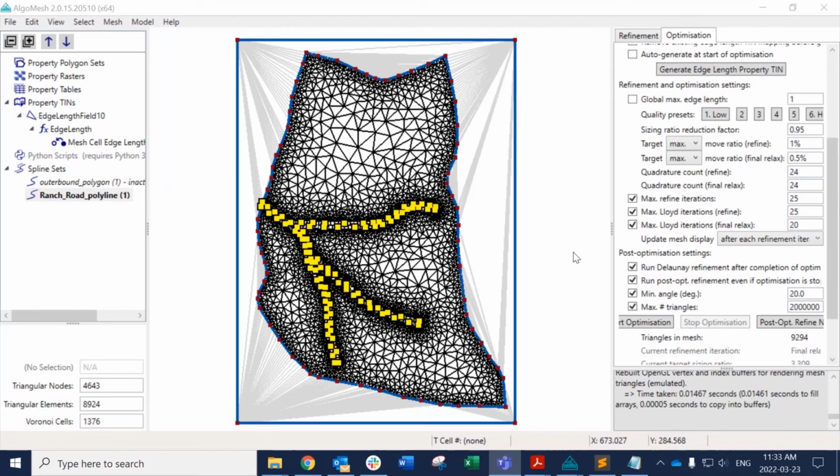I used to work a lot with ModFlow. I was actually the salesperson for Visual ModFlow for many years. I can say that HydroGeoSphere does pretty much everything that every generation of ModFlow engines can do, and it does them all together: surface flow, groundwater flow, variably saturated flow, contaminant transport, fracture flow, flow through 1D hydraulic features like channels and tile drains, and density dependent flow.